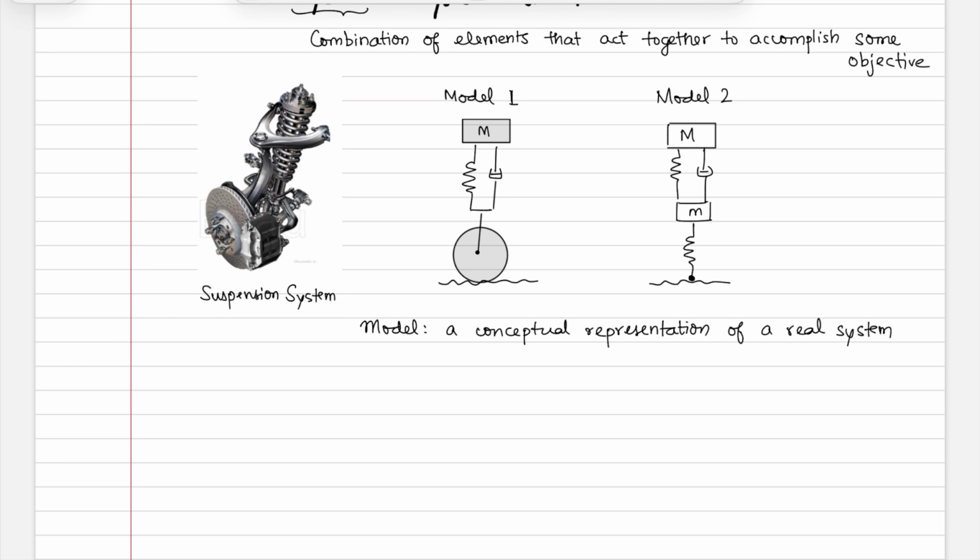Okay. So in engineering, these concepts are formalized through physical tools such as, you could have a scaled prototype and you can actually do a test. So, for example, if you're in aerodynamics, you might have a scaled model of your full scale aircraft, and then you put that into a wind tunnel, and that is again a model. It's a representation of that real world system. And now, when you have it in a scale of, say, 1 is to 10, you then have to account for the Reynolds number to be able to make use of your results from experiments to actually make decisions for your full scale aircraft. Okay, that's just a conversation about how it can also be a scale prototype.